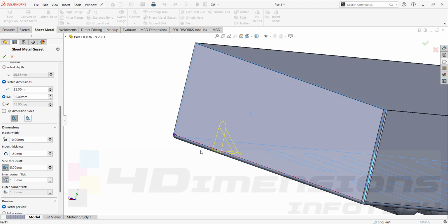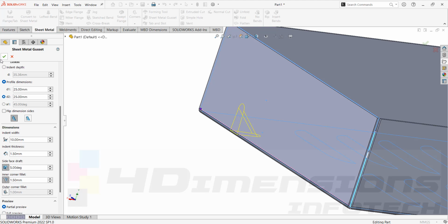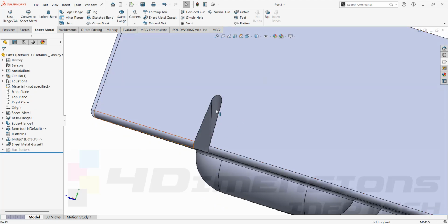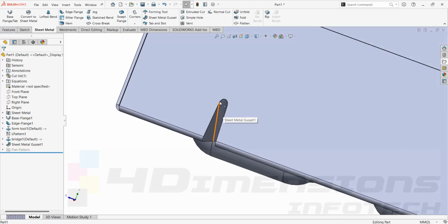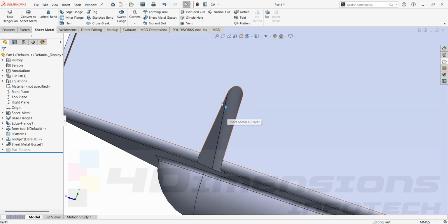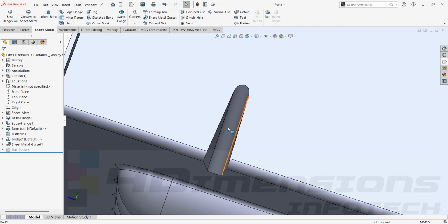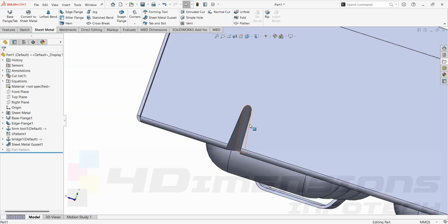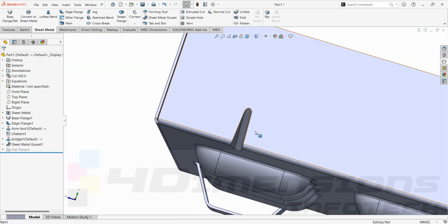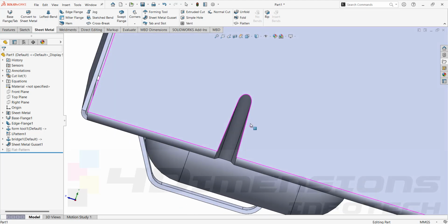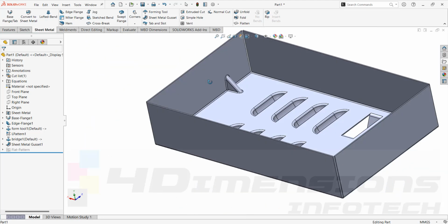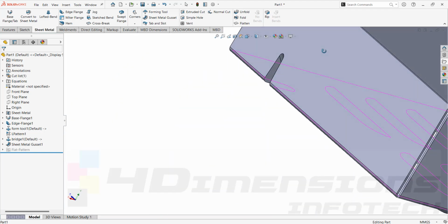So when you punch this part, to withdraw the die which we have punched to make this cavity, if the die does not have any fillets or tapered angle, it may damage the part, create cracks or cut the part, as it is a thin sheet metal part. That's why drafted faces are provided for easy withdrawal of the tool or die.